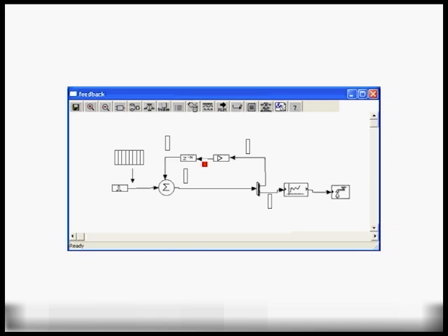So the delay doesn't have a sample at the input, so if you just leave it at that, it will not generate a sample. And the add block looks at this and it sees that it has samples over here but no sample here, so it will not generate anything. And after a while, the simulation deadlocks because there'll be a situation where none of the blocks have samples to process and they don't output samples, and that's called a deadlock, and the simulation halts.